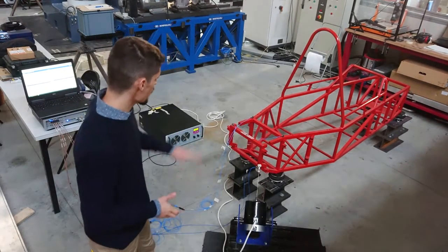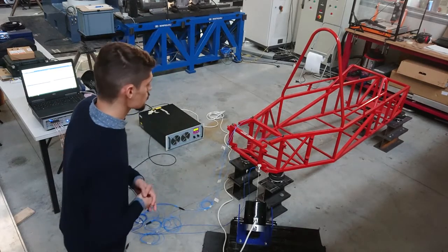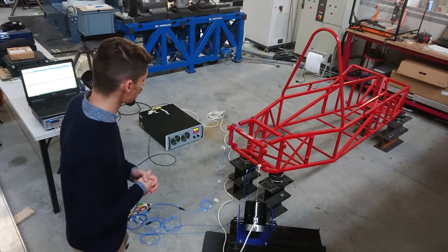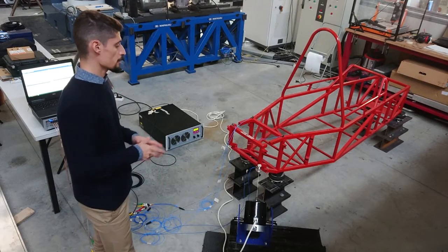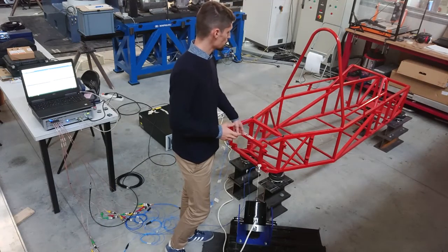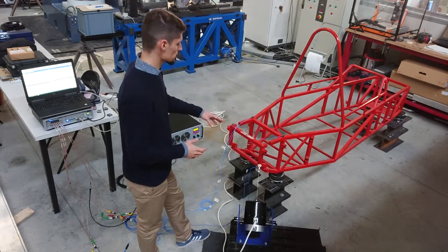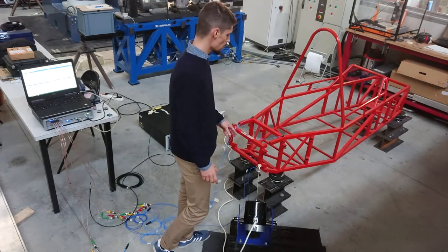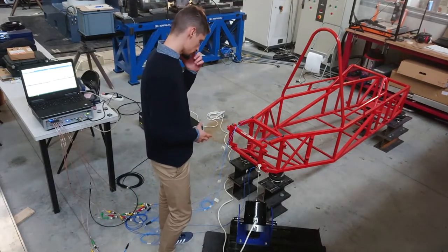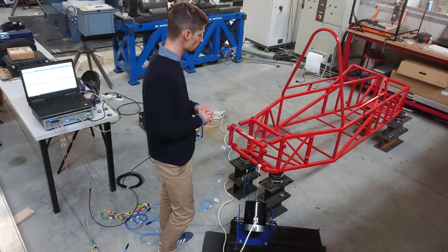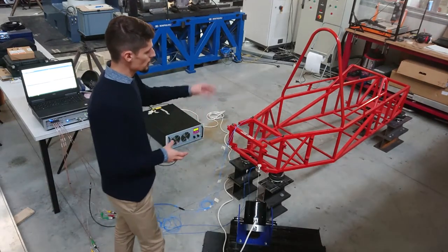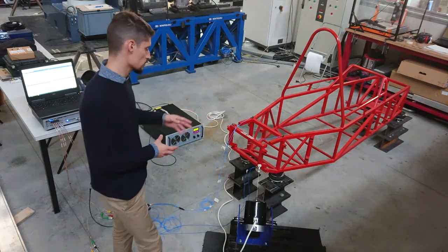Okay, we have already seen everything about the test equipment, so let's start to talk about how to perform the modal analysis. The first step is to define the measuring points. I mean, we should discretize our structure in a point grid. These points are the points where we will attach the accelerometers for measuring the responses of our structure. And therefore, the definition of these points is very important for estimating the correct FRF and for catching all the possible mode shapes of our structure.